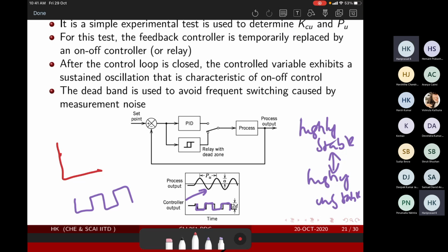Output would be very slow. So let's say it is here, it would just come down and go up, come down, go up. For instance, consider an AC with an auto cutoff limit, not the inverter one. When it cuts off, when things are cold, the temperature remains a little bit. Then it comes down. When it becomes low, it restarts. And when it becomes high, it goes up and cuts off. Then it would stay and again cut off.